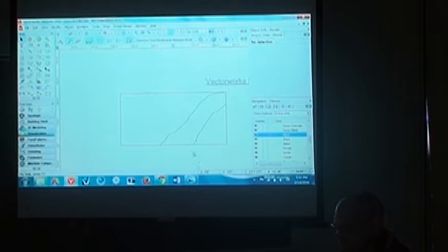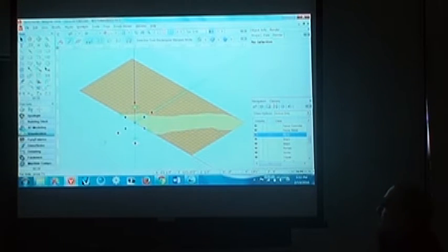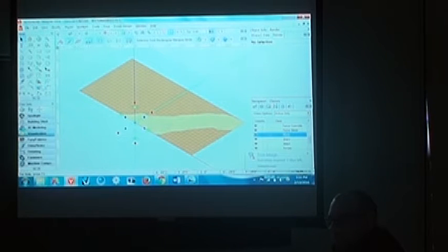So this is the floor, the ground of my set. It's just two extrudes, one to make kind of a road area and then one to be the painted surface of the floor. Right now we're looking at an OpenGL rendering with just the fill color. There are no textures or anything applied. So what if I want that to look more realistic? I want it to look like dirt. I want it to look like a stone gravel road. Then what I can do is create a custom texture and apply it to those objects.